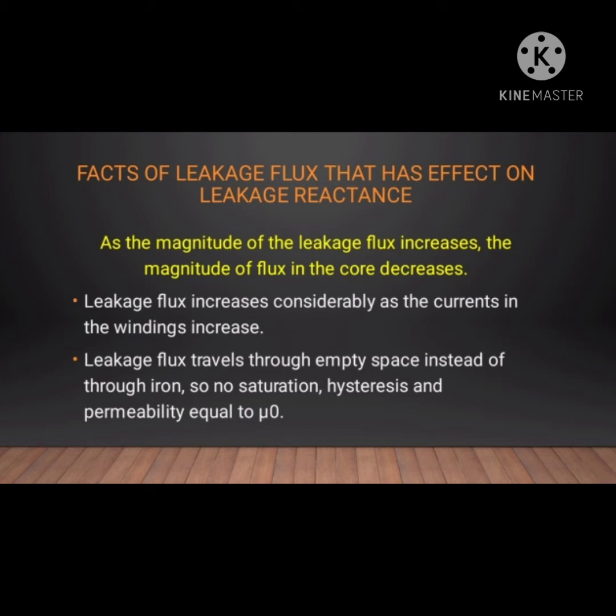Leakage flux increases considerably as the current in the winding increases. Leakage flux travels through empty space instead of iron, so no saturation, no hysteresis, and permeability equal to mu0.